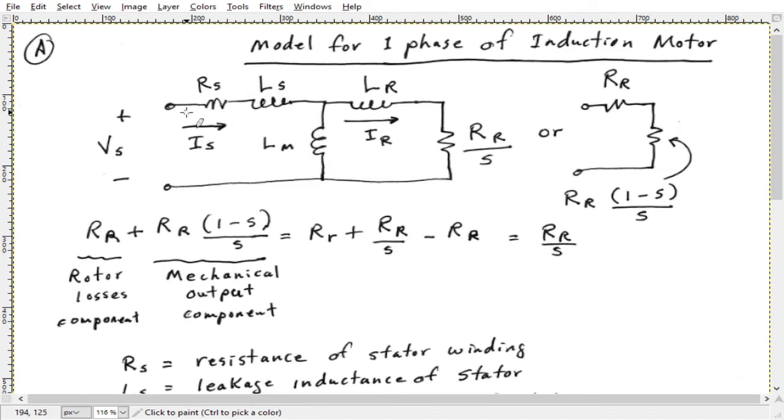So predominantly an inductive current is flowing here. Remember, Eli the Iceman: voltage leads current in an inductive circuit. This would be mostly inductive, so the current would be lagging the voltage, and this would be 0. Now let's look at the other extreme case.